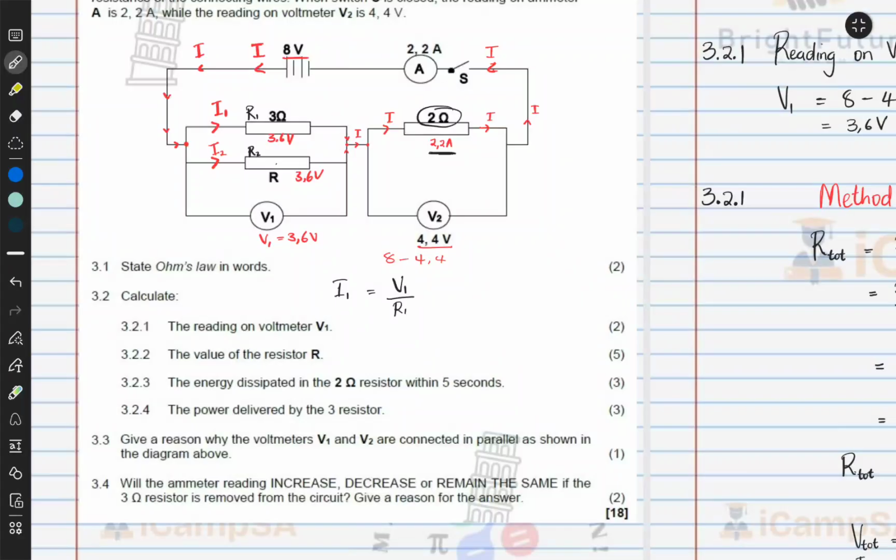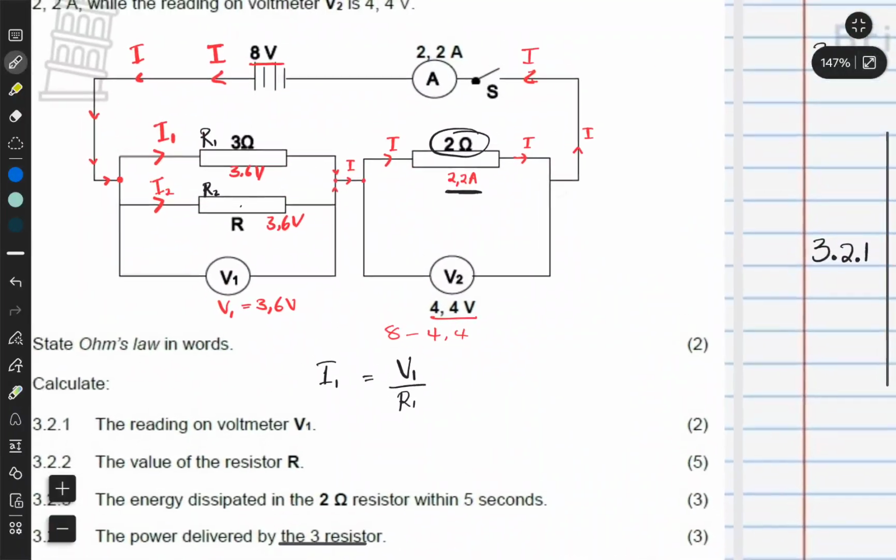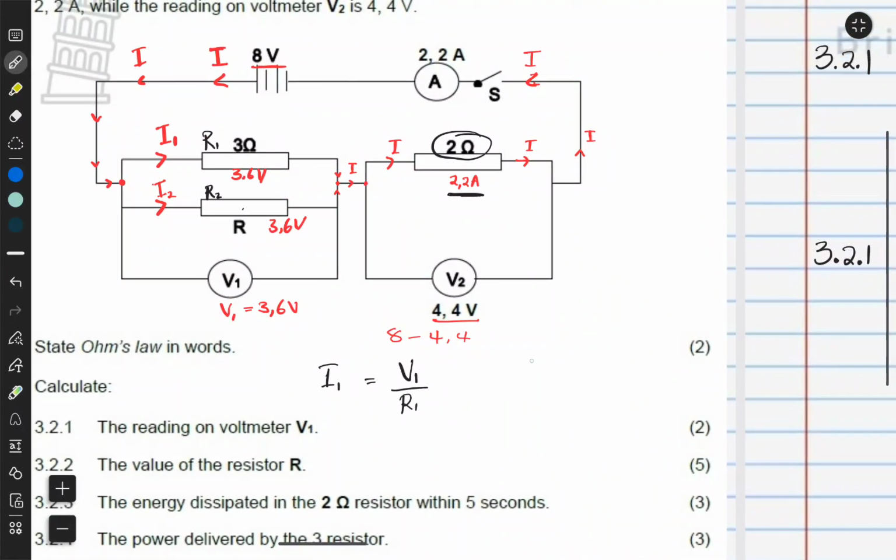So that's why, because it measures the potential difference and it has a high resistance. So unlike an ammeter, a voltmeter has to measure between 2 points like this. So it measures here and there. So the difference in potential, in electric potential. So it has to be connected like that.